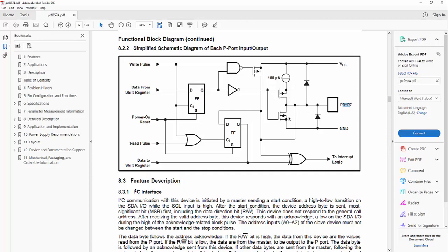We have here the MOSFETs, which are N channel and P channel. This is like a NOT gate. So if this is a NOT gate, we have another NOT gate. NOT gate and NOT gate cancel each other, meaning if I'm writing 1, I will get 1 at the output. If I'm driving 0, NOT and NOT again will give 0 at the output.